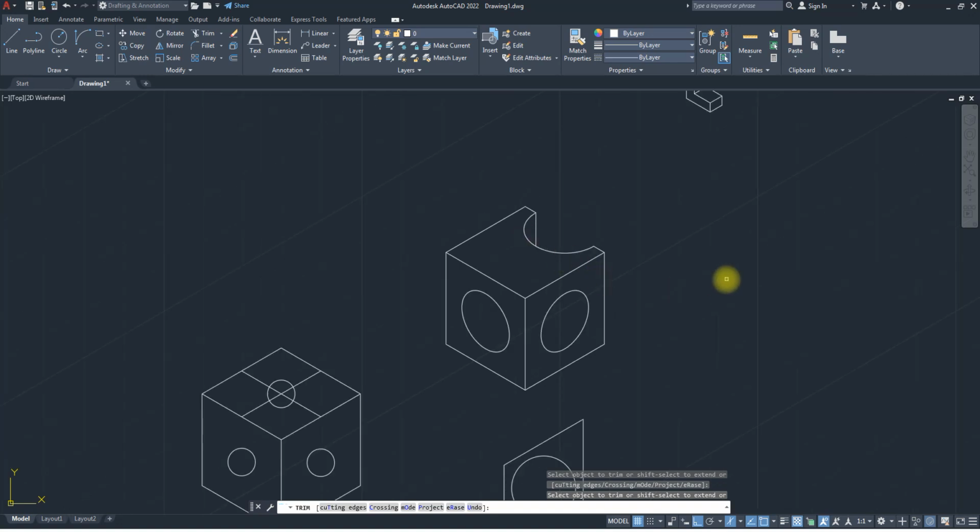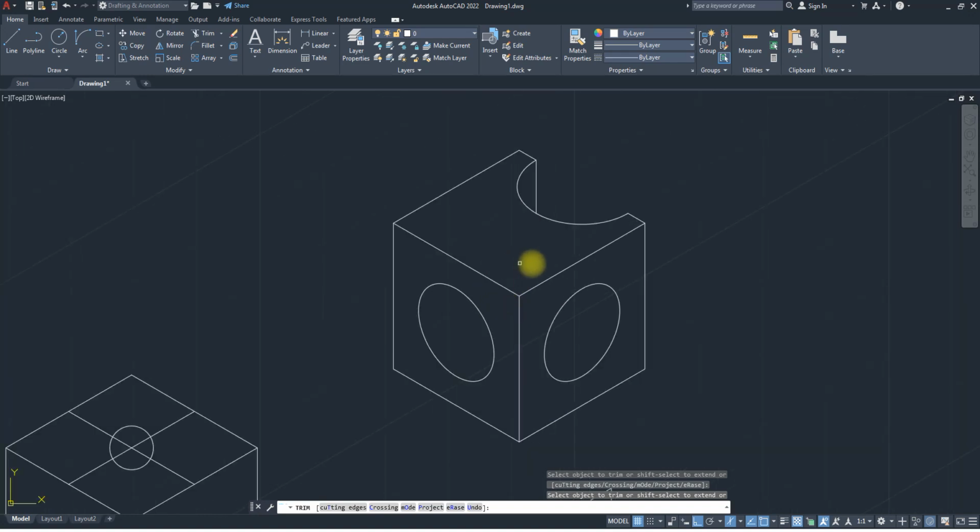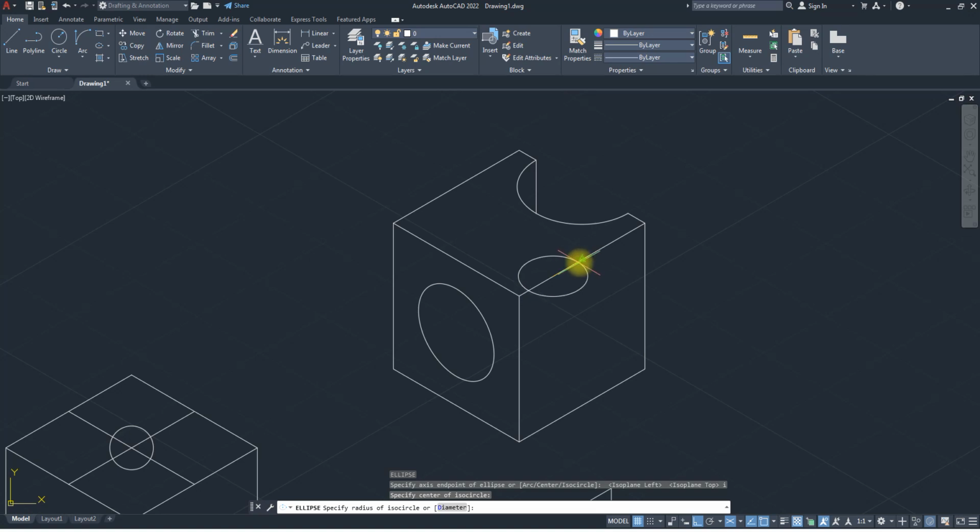Do you understand? If I look at this surface, I'm looking at it from this point. I should be able to see that point. So that's what this is. If I want to do the same thing here, maybe I want to create a chiseling somewhere here or somewhere here, I can also do it. Okay, so that means if I go to my ellipse, change my view to top, pick from here, choose my I for ISO, which is very important, pick from here all the way to this place. Then I can trim.